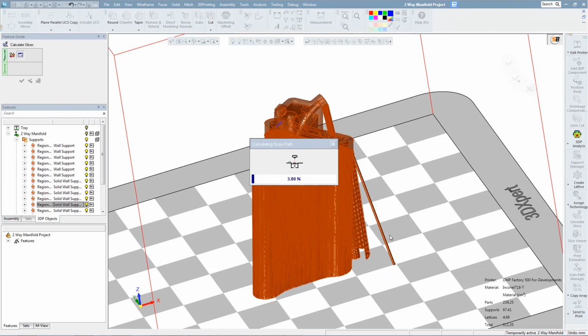Two other issues I would like to touch on quickly are 3D zoning and offloading calculation. 3D zoning is a patent-pending technology included with 3D Expert. It allows you to create virtual 3D volumes and assign specific build parameters to it without splitting the part. This allows you to define special build parameters for thin area, concentric slicing, and rough slicing without forming a weak point in the part. Offloading calculation allows you to add slicing machines in a private cloud to which you can offload the slicing and enhance slicing speed dramatically. If you want to hear more about any of these topics, please contact us after the webinar.